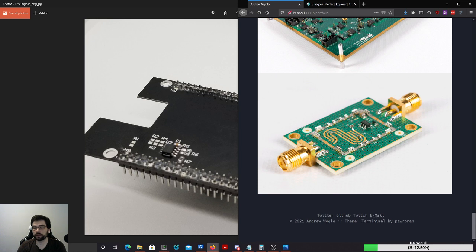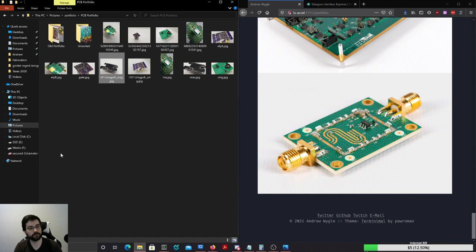Anyway, so yeah, coplanar waveguide. This is single-ended coplanar waveguide, but you can do a grounded differential coplanar waveguide, and then you can have your nice thick board and still hit your impedance targets. The only problem is that at the time I didn't know where I could find a calculator that would do that for me. Let me pull it up.